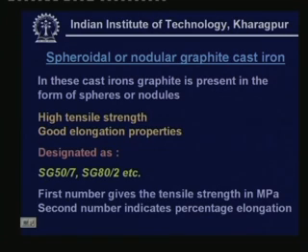Later on you will see that truly ductile materials, like mild steel, which we will be talking about, normally have percentage elongations much more, maybe more than 10. Still, you can see this has a good amount of percentage elongation, while the second one does not, it is only 2%.